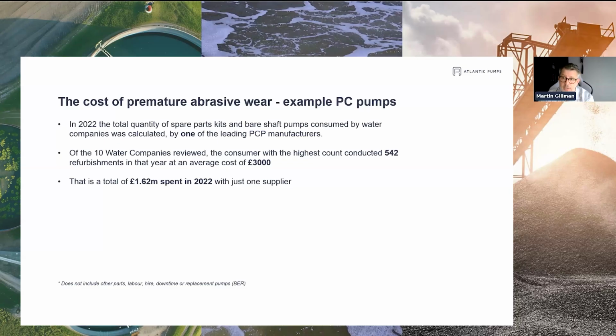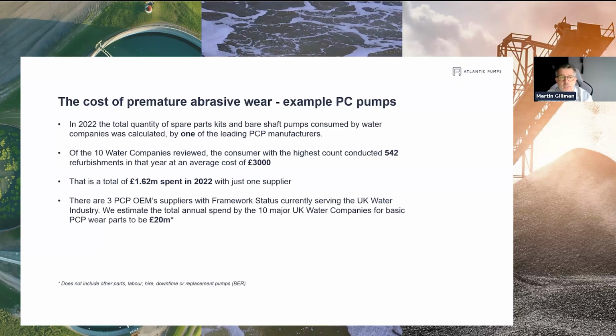So you could argue that of those 542 pumps, maybe a third had come to some reasonable point in their wear life, and the maintenance intervention was timely. But probably, and again, I'm just speaking from experience, using a little bit of guesswork here, but it's quite well informed, about 2/3 of those were premature. So we're looking to avoid that by better decision making.